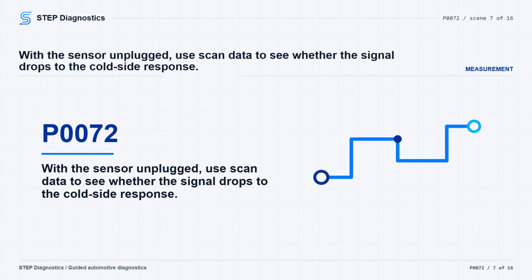For circuit testing, turn the ignition and vehicle off and let all vehicle systems power down. It may take up to 2 minutes before a ground or low reference continuity test is accurate. Disconnect the B9 ambient air temperature sensor connector. Test between low reference circuit terminal B or terminal 2 and ground. You want less than 10 ohms.